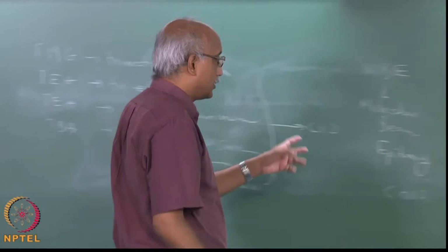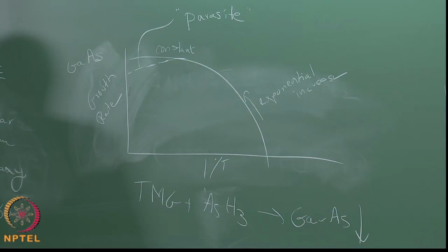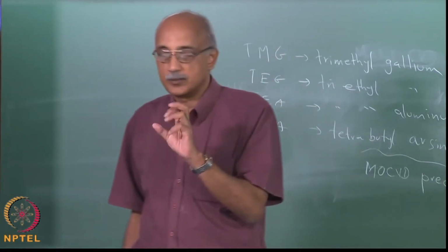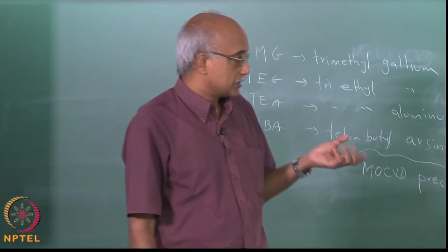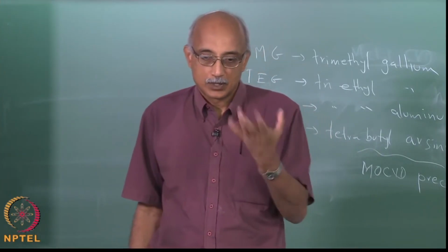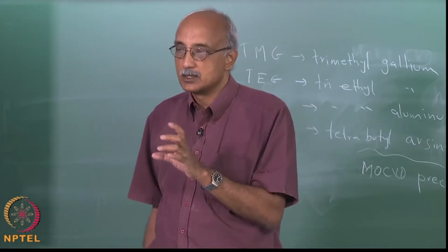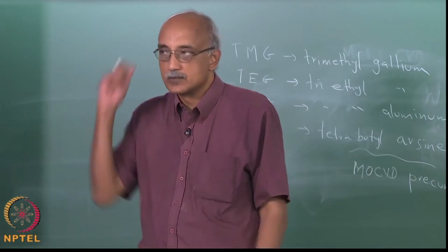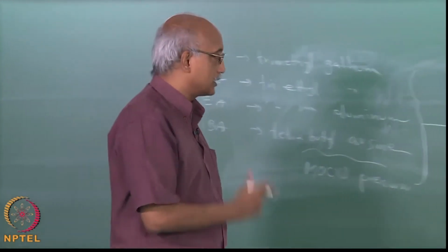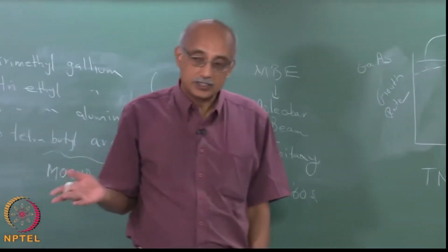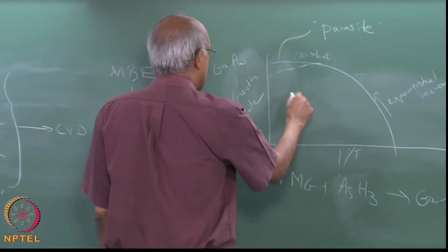When we look at the growth rate of the deposit, the overall thickness may be increasing as a function of time, but the composition may be changing. Whereas, when the depositing elements are removed and kept in the vapor phase, you will see a net reduction in the rate of film formation itself. And that is one reason why you do not want to operate in this range.